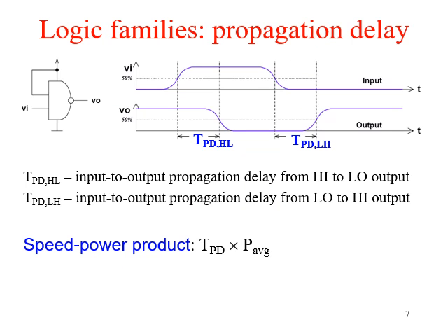The next parameter, which is a very important feature for a logic family, is the propagation delay. Let us try to understand what the propagation delay is. In general language, if there is a gate, like a NAND gate for example, the time the input takes to propagate to the output side is referred to as propagation delay. This occurs because there are certain components used in between which have some inherent delay in them.